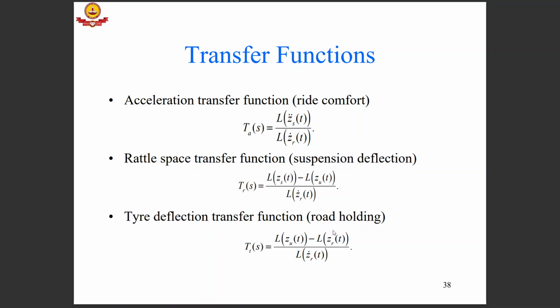So these three transfer functions are going to behave in a different way for a given input. The idea is to minimize all three in such a way that it fulfills the objective, in some optimal sense. For example, we had Fa, which is the active force. We can modify that Fa in order to obtain better characteristics in each one of these depending upon the operating condition.